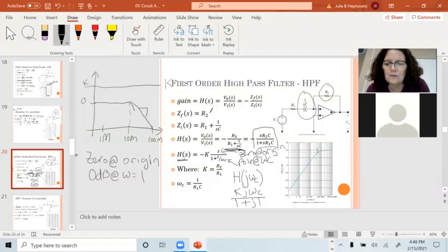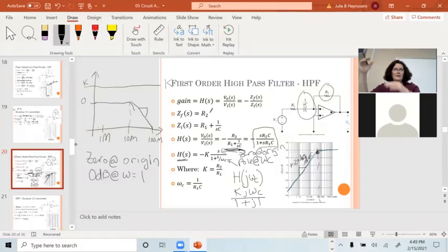So the way these high-pass filters work is you don't plot the components because you can't do that 0. You just plug in omega c, you get minus 3 dB, you know that's your cutoff frequency. It's going to be flat after that, and it's going to be positive 20 dB per decade going up to it. It's a shortcut to avoid having to plot that third thing that you can't plot on that graph. I've seen all kinds of crazy ways of people making the math really hard on that. The easiest thing is just say, okay, what's going on at omega C, and know the shape of the curves. And this will be whatever K is, 20 log of K. Okay, I will be in the lab when that happens.